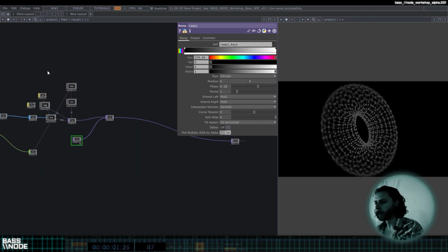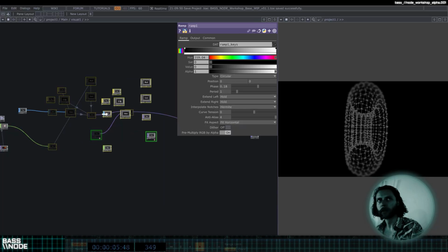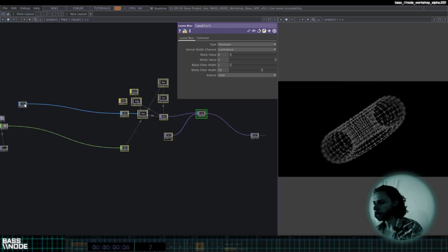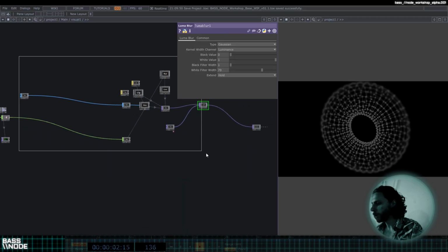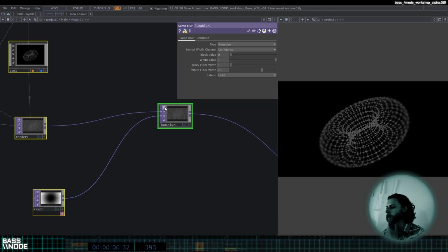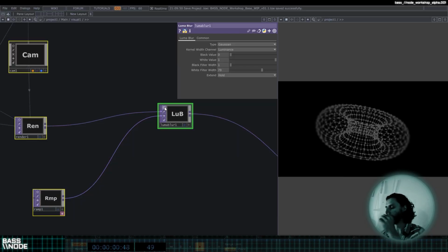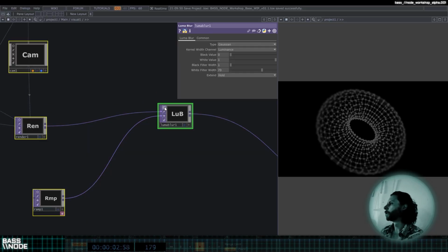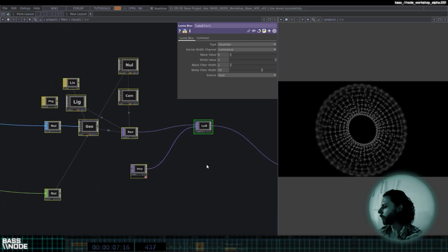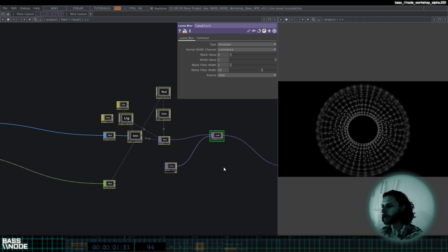I'm gonna just organize my network a little bit more by dragging everything. I'm gonna leave this torus over here alone. And I also just hid the viewers. So with this button, you can toggle your viewers to be active or inactive. And they actually use up a lot of resources in TouchDesigner. So if you're struggling a bit, turning those off can sometimes give you all the boost you need to get back to 60 frames a second.